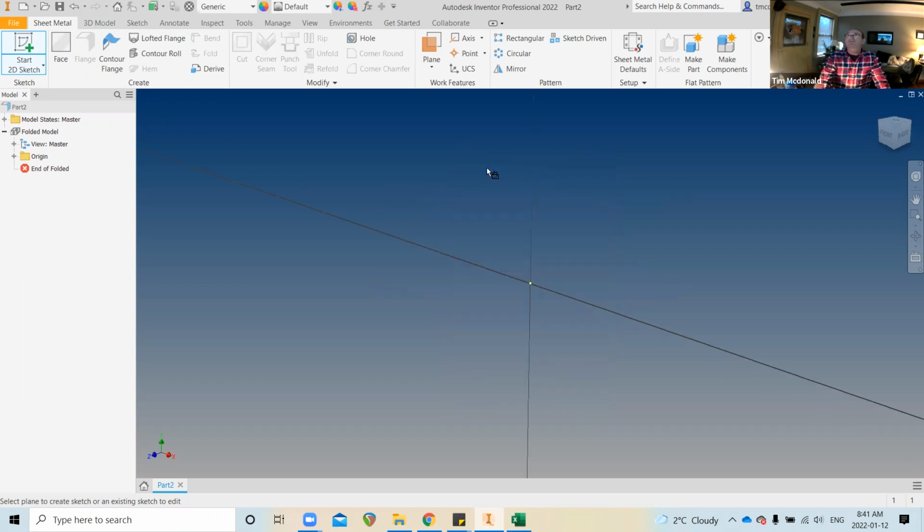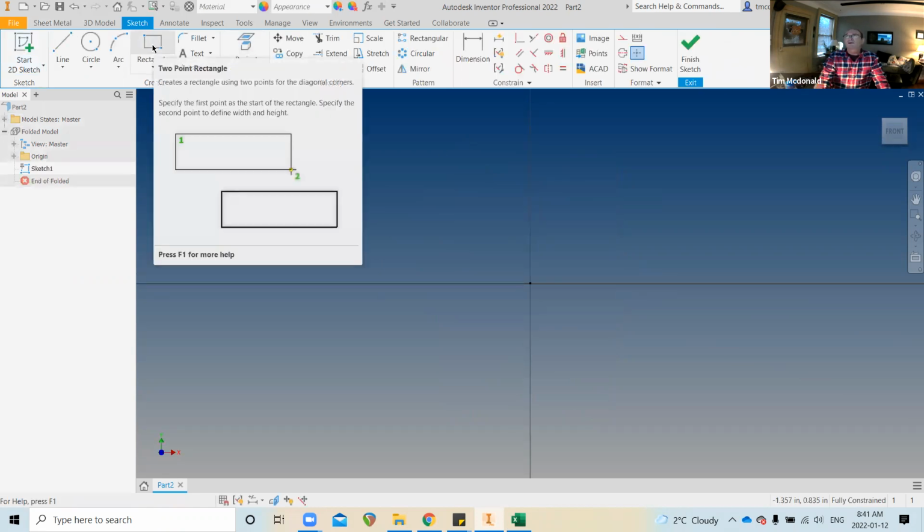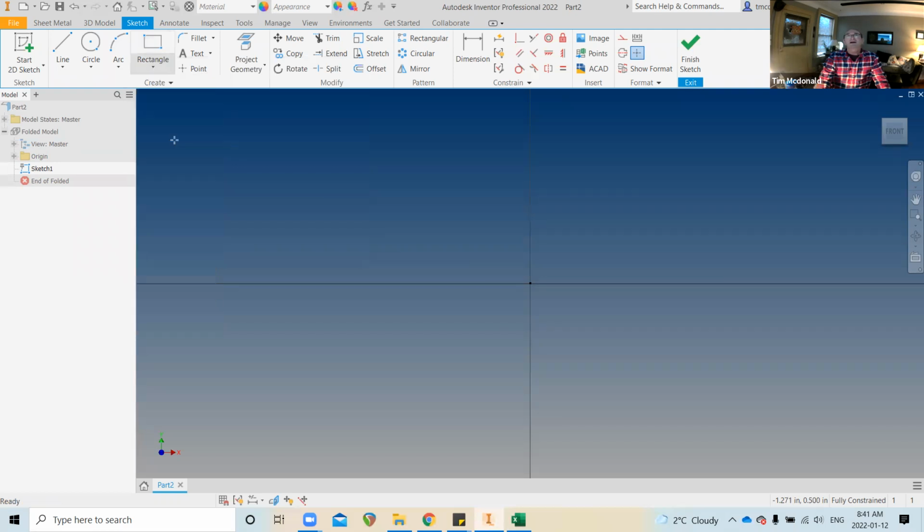So I'm going to create a sketch on the XY plane. And let's start with, do I want a center rectangle for this? Maybe I'll use a center rectangle for the base. Yeah, let's use a center rectangle because I like the center rectangle. When you use a center rectangle, it just makes it very easy to grab the origin of this workspace and use that as your origin for your component. I'm just going to escape the command here for a second.